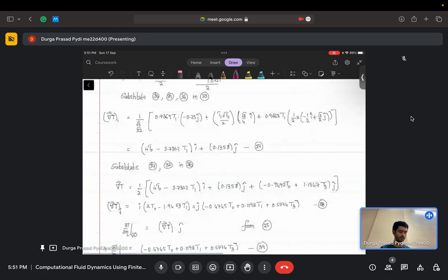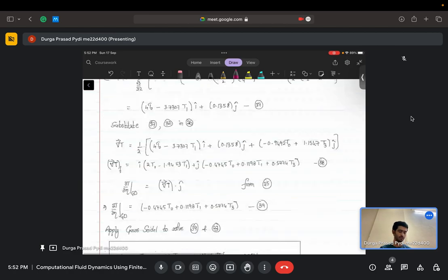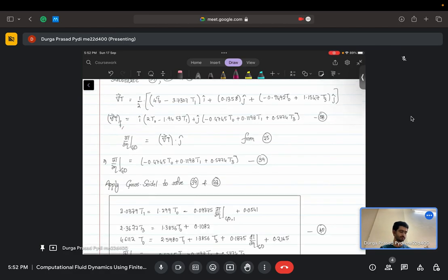So I will get a value of gradient along for the cell 1. So once I know the gradients along cell 0 and cell 1, we will just take an average of them to get the gradient along the face. Face is GD here. So for face GD,